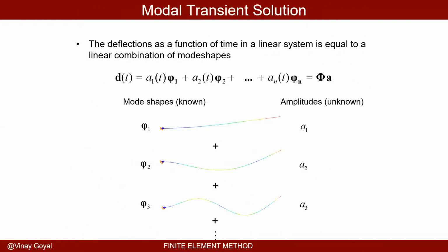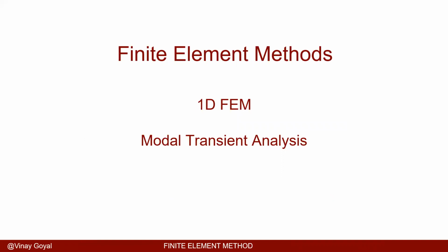Because in lecture 14, we talked about having to solve a problem by integrating over the domain for a fairly large system potentially. But in this lecture, I'm teaching you that you can use the modal frequencies, the eigenfrequencies and mode shapes to really simplify the problem a lot more. It's an approximation, of course, and it only works for linear systems or close to linear systems. And it can be a very powerful tool to solve transient problems in a very effective manner.